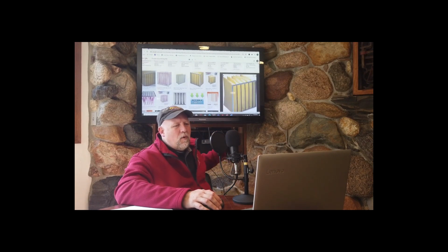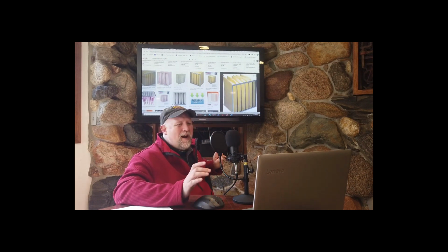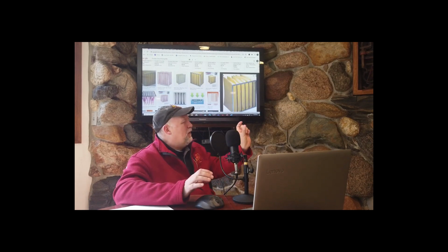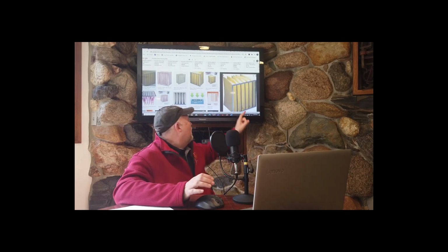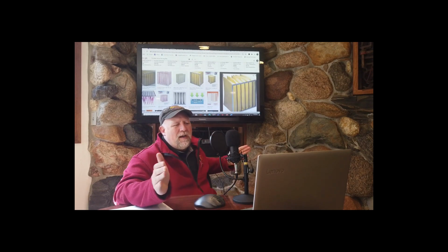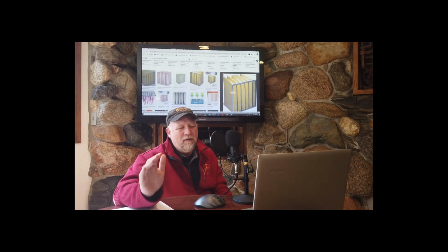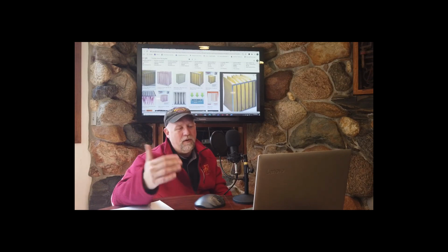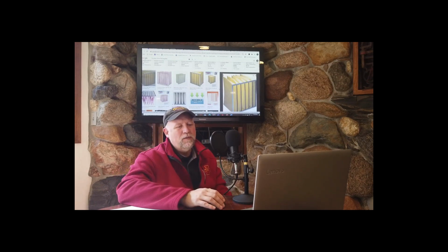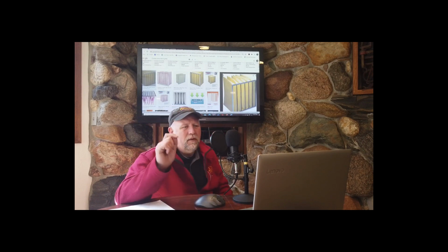Something important to notice here. One, these get more expensive because there's just physically more media that we're purchasing. Two, in the air handler itself, whereas that pleated filter only takes up 2 inches of thickness, this is going to take like a foot or 2. So it makes our overall air handler much longer and also more expensive and takes up more space. Whether you put that air handler inside in a mechanical room or on the roof, it just got bigger and therefore more expensive. But these bag filters will have less pressure drop and you won't have to replace them as frequently as you will the pleated ones.